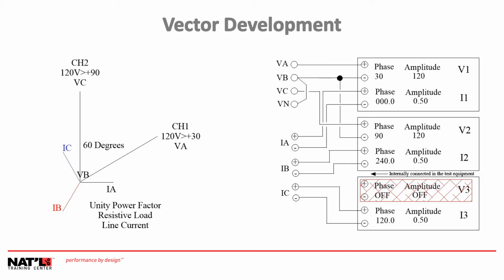However, what I wanted to point out here specifically has to do with the voltage connections on the relay. Most relays for switchgear and meters will have a designation similar to this, VA, VB, VC, and VN. It allows for a Y-connected set of PTs, a delta-connected set of PTs, or an open delta-connected set of PTs. So in this case here, we're using our open delta.